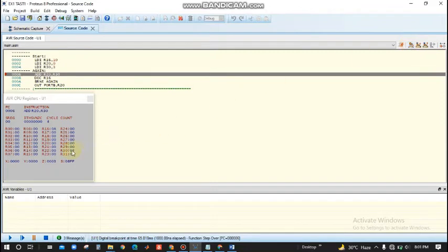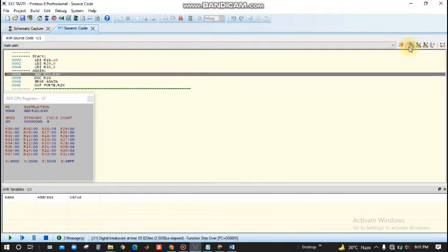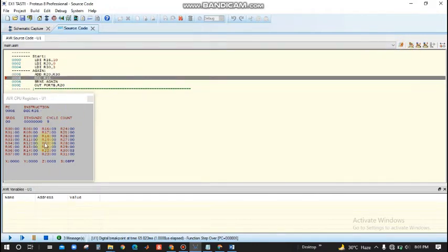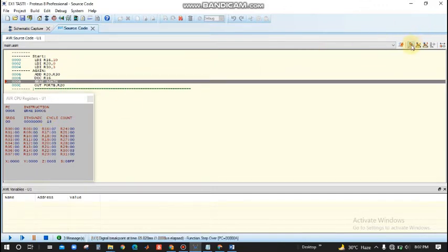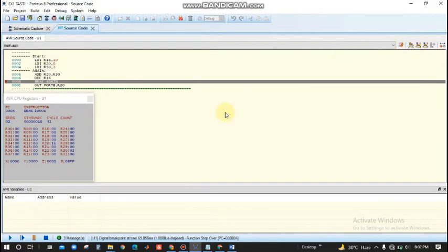So here the code is compiled successfully, and let's debug it, and let's see how the CPU registers show us its working. 2-3 things that we will be focusing on: R16, R20 and R30. So basically the change will come into R20, and R30 will obviously be the same. You will see it now. R30 is 3. So after this we will reach BRNE again in the next step.